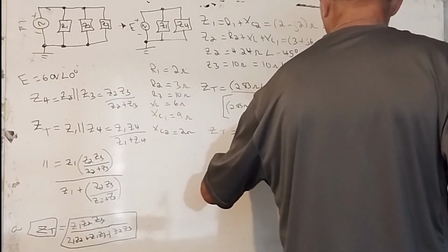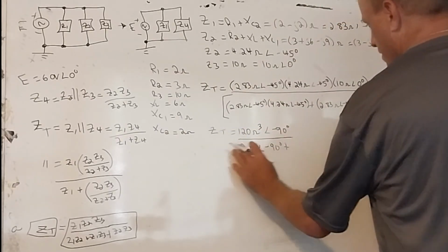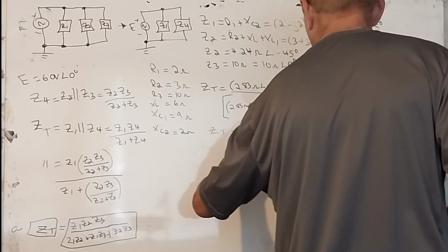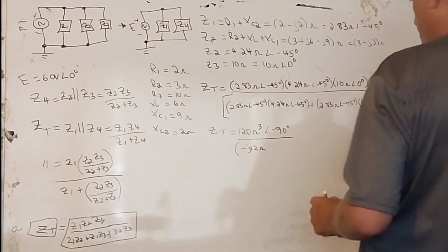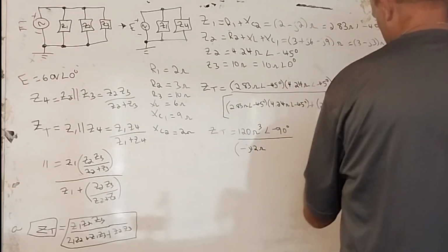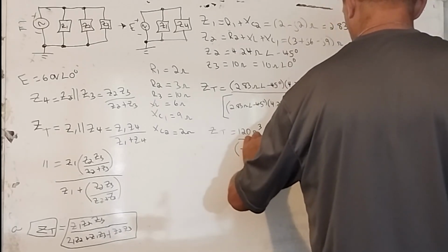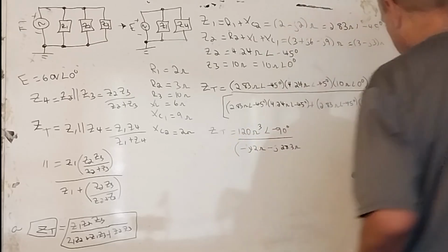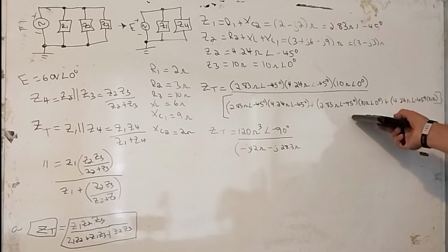And that's at an angle of negative 90 degrees, and I'm going to write that as negative J12 ohms, because we're going to add all these values together, so it's better to have them in that notation. This is pretty easy, 28.3, and we're going to subtract that, so minus J of 28.3 ohms, multiplying 10 by 2.83, at negative 45 degrees.